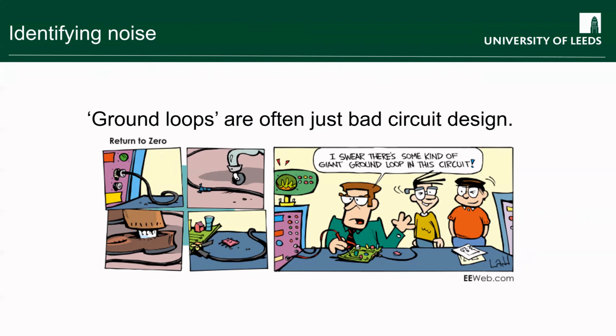So if you've got a problem, check your cables carefully, check that the connectors are on securely and that there's no obvious sign of a break. Generally speaking, you can undo a cable and look at how the wires are soldered into the connector and check that they're mechanically strong. If a soldered joint is mechanically strong, it's almost certainly good electrically. Then check for physical damage on the cabling itself, and then you can check with a multimeter that things conduct all the way through. Pretty much the first thing you always want to do is try changing your cables over and see if that makes things better before you start disputing what's going on.